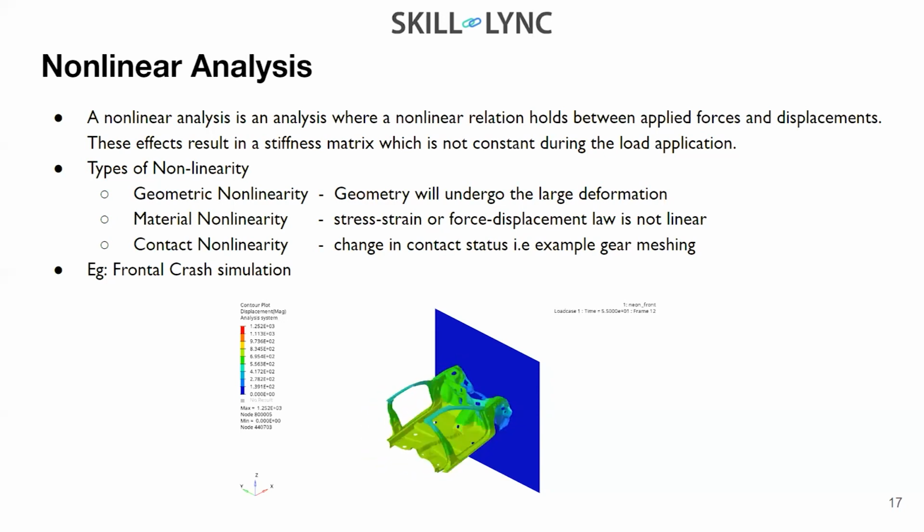That is why people have come up with the BIW, or the outer car body, being flexible. Now that flexibility should not be too much either. If it is too much, what will happen? Suppose you are sitting in a car made of a very deformable material like sponge. It will simply crush you. We don't want that either.